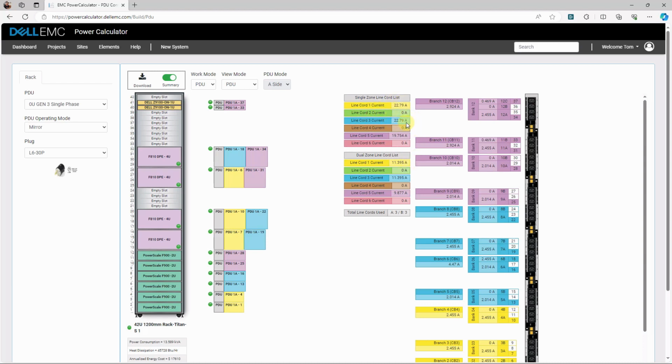So the other thing this chart is nice for is now you can look at how your cords are loaded. So now I can see I pretty evenly got my amperage, the current, going pretty evenly amongst all these cords. So this is an optimal configuration, right? And I'm not going to lie to you, I went through this a couple times. I didn't do this the first shot through this. It's going to take a couple times of you playing around.